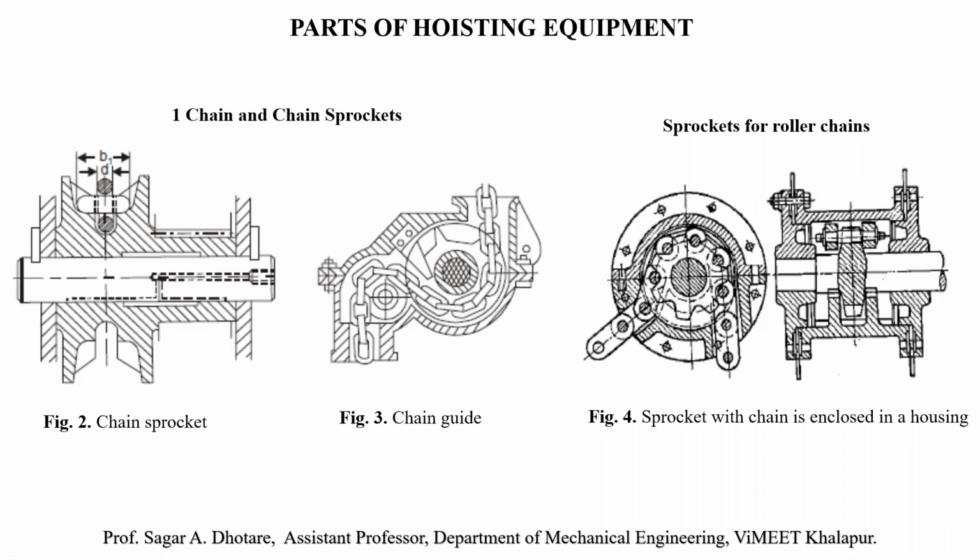A variety of equipment falls under the head of hoisting equipment, starting from hoists, different types of elevators and cranes. With the exception of elevators, these equipments generally utilize a drum, a wire rope, pulleys, and load lifting attachments for performing the lifting and lowering motion. The hoisting equipment can be stationary, portable or traveling type.